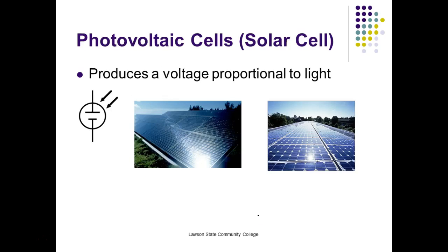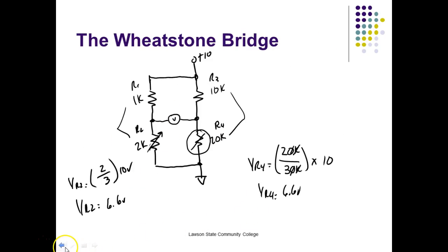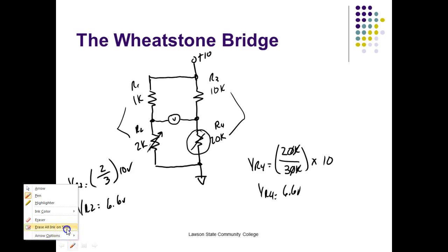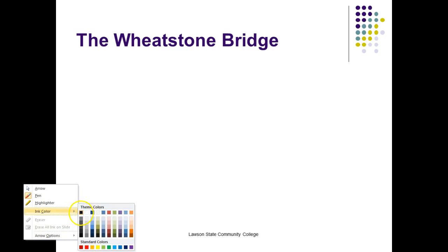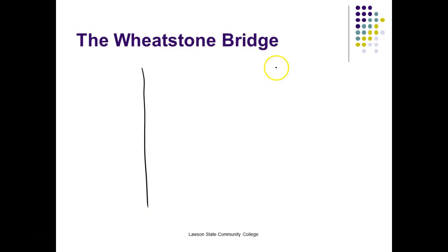And let me go back to my Wheatstone Bridge where I have a blank sheet. So in electrical controls, we come over here and, y'all had motor controls? Okay. Motor controls is basically we come up here and we have two circuits. Generically we call this L1 and L2, but that's my power. L2 is considered the common, and then L1 is considered to be what we'll just call the hot. And we connect circuits between these two rails.